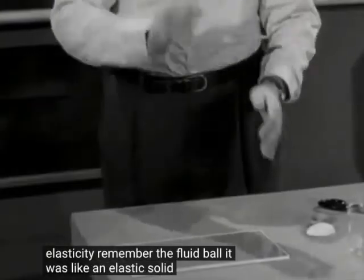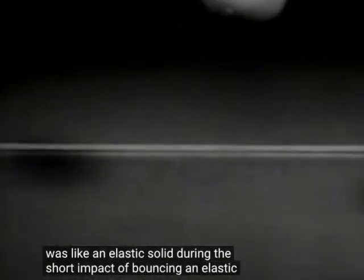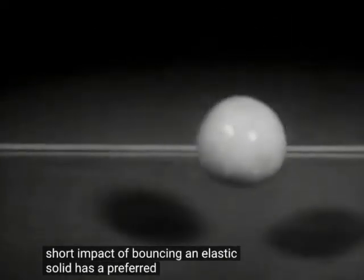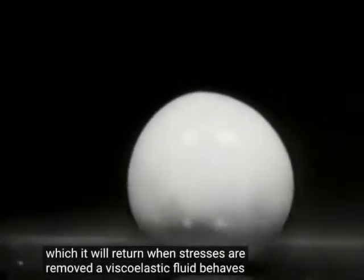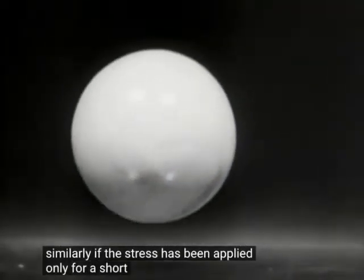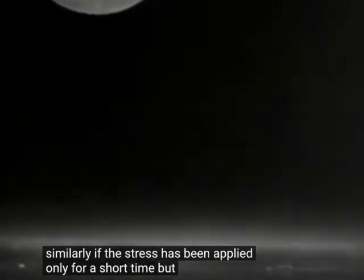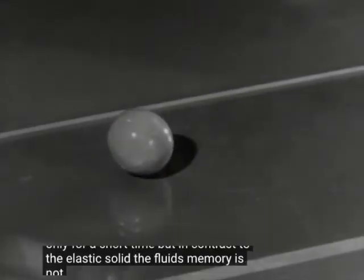It was like an elastic solid during the short impact of bouncing. An elastic solid has a preferred configuration to which it will return when stresses are removed. A viscoelastic fluid behaves similarly if the stress has been applied only for a short time. But in contrast to the elastic solid, the fluid's memory is not perfect.